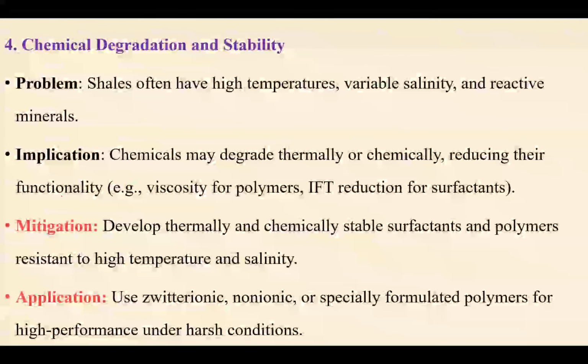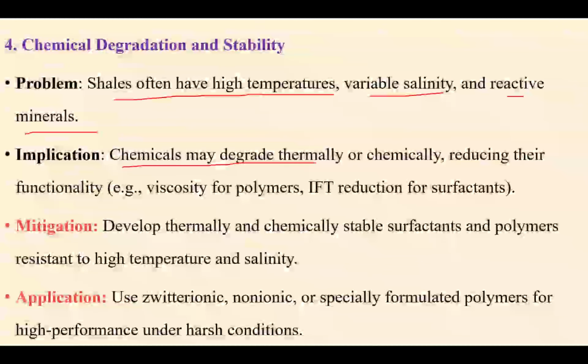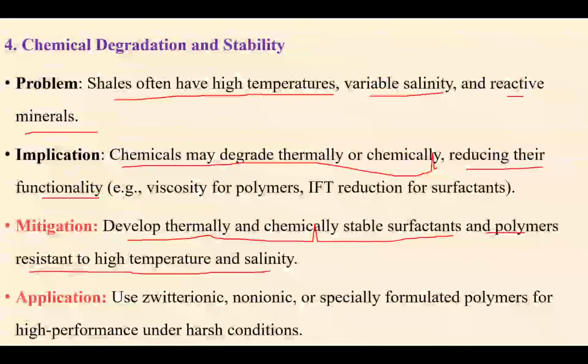Now the degradation and stability. Shales often have very high temperature, variable salinity, and reactive minerals. So the chemicals may degrade thermally and chemically and reduce their functionality. Accordingly, you have to develop thermally and chemically stable surfactants and polymers that show resistance to the high temperature and salinity conditions.